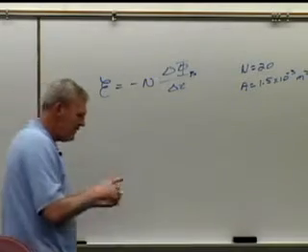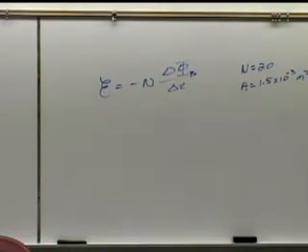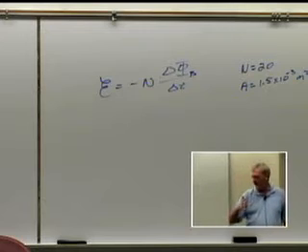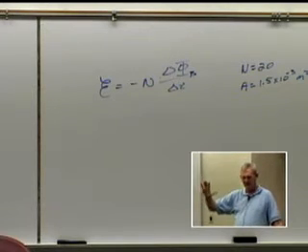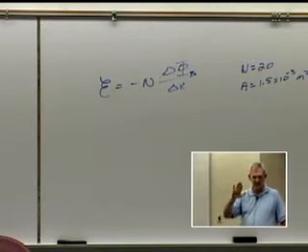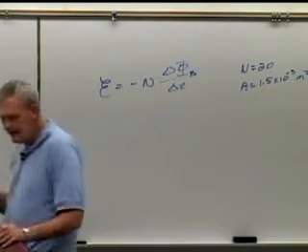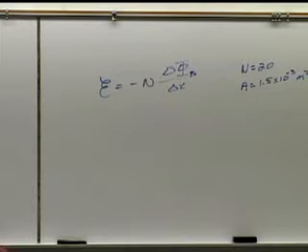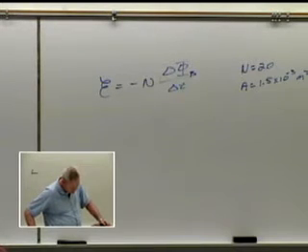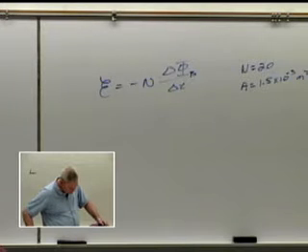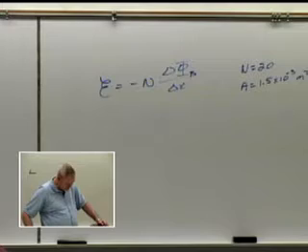So that means when this loop turns, it's not turning away from the magnetic field like when I was showing you down here. The magnetic field is always going to be perpendicular to it, so that means B's not going to change. And theta equals 0 at time t equals 0. The magnitude of the field at the location of the coil is B naught.